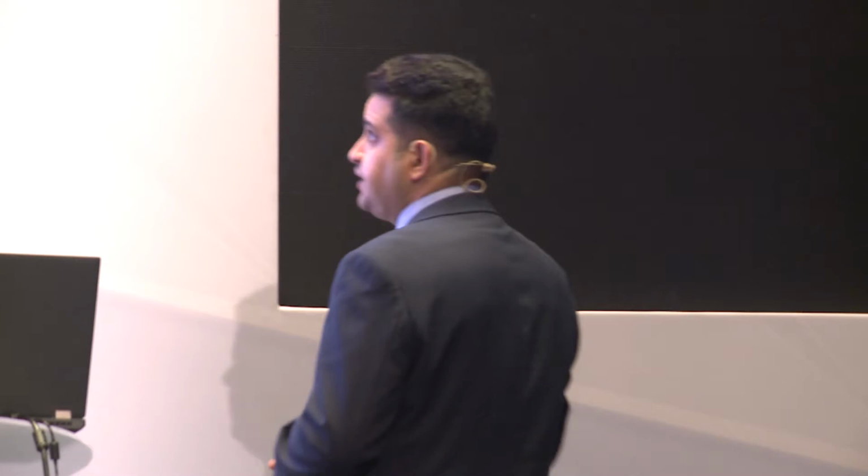Now, the robotic total station, the one which will be used with this application, is a one-man job, and frankly speaking, you do not need to have surveying experience as well. If you are a BIM guy, your model is fully coordinated, you know exactly this is the point I'm going to construct. You can connect this application with a robotic total station, and it will take you to exact points for structure, for MEP, as well as architecture elements which you need to connect. So that's going to be a very easy workflow over there.